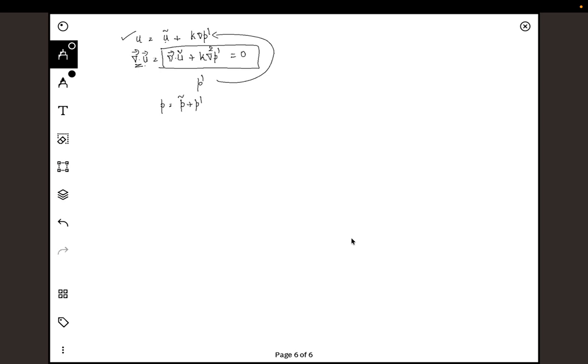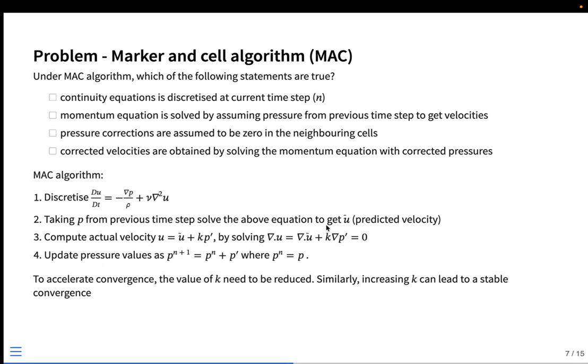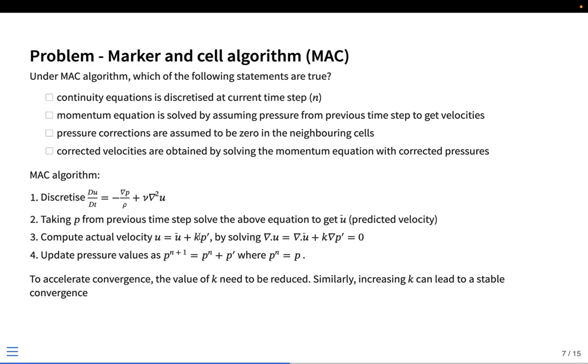So you start with an assumed pressure profile, solve the momentum equation, and then update the velocity. There should be a del term here that is missing. I'll correct this before the final update. And then we will solve for this continuity equation together. When you solve this continuity, we'll have a Laplace term here. Instead of del, it will be del square. You have to solve for p prime. Once you have p prime, you can get u and p, and then you keep iterating. For example, if it is a transient problem, then you will keep iterating till whatever time step you want.